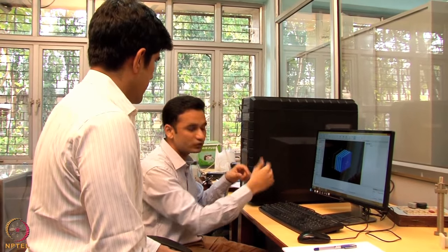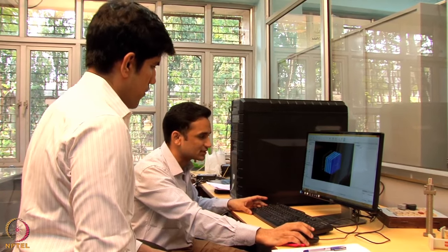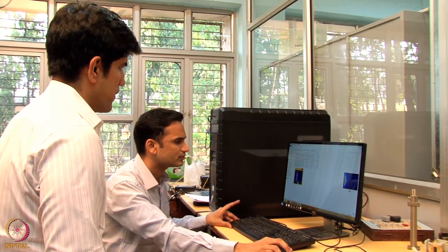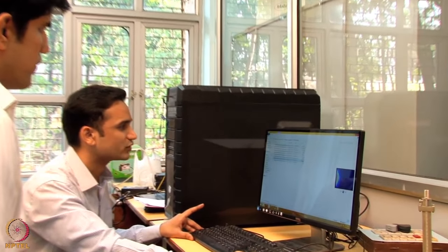We will be looking at the 2D simulation of that and we'll see the window. So you have translated the 3D problem into a 2D problem and are simulating it. Show us first the 3 cells per wavelength. This simulation is for lambda by 3 discretization. The light is coming in this direction, and we are recording transmittance here. We'll be recording reflectance at the back of the source.